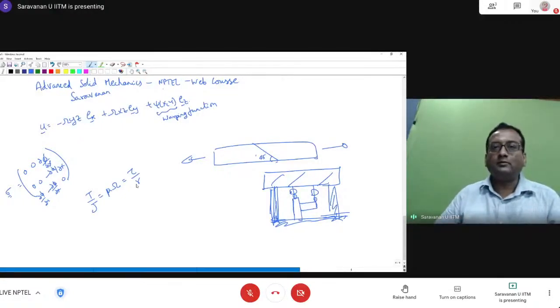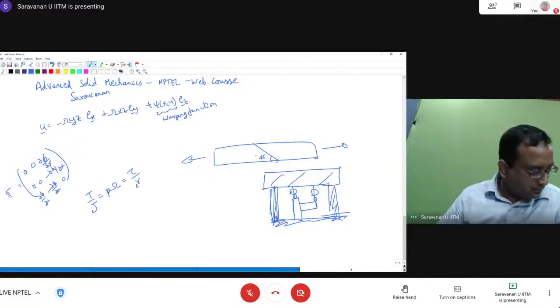And that is violated, which is the case in most sections. You can't use the elementary theory to predict the response of the structure due to torsion. It's very approximate. You have to appeal to theory of elasticity to be able to get an accurate expression for torsional moments.